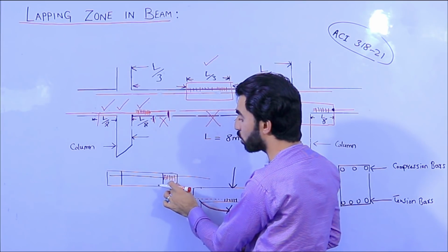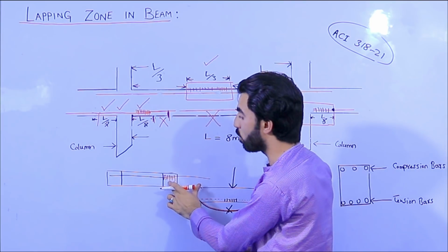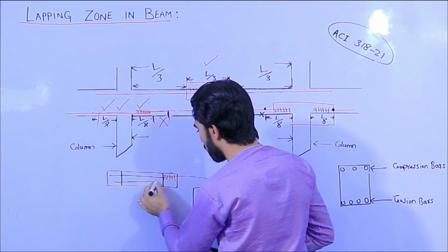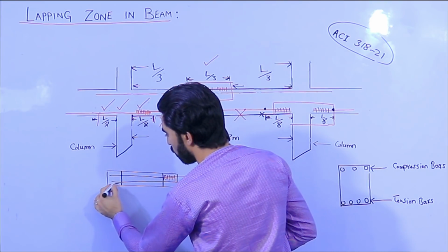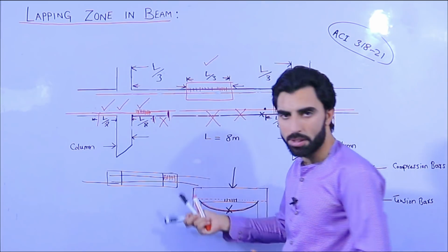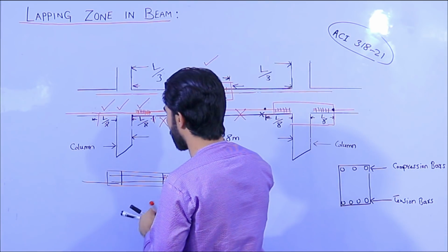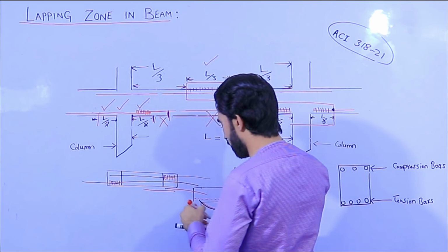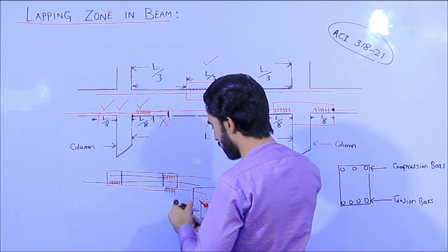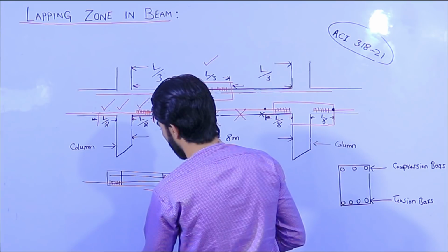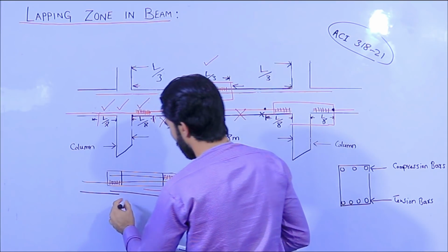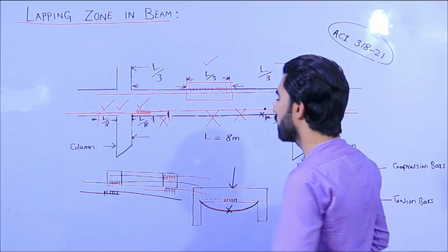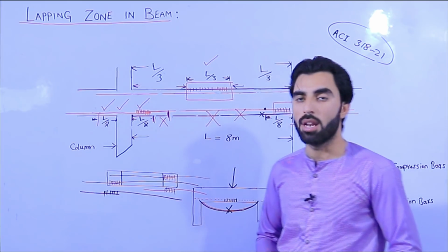But the other steel bar should not be provided or overlapped at the same point; the other should be provided same like this, as you can see. Here it will overlap to this side, because we have more length in the building, in the steel structure, so the other steel bar should overlap here. Now the other will overlap same like this here, and also this one, for example, like this. So at the same point we cannot provide lapping length.